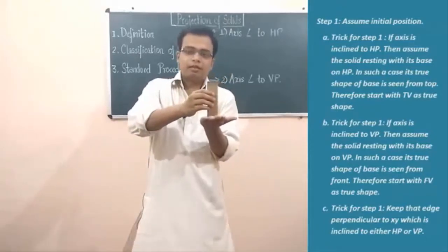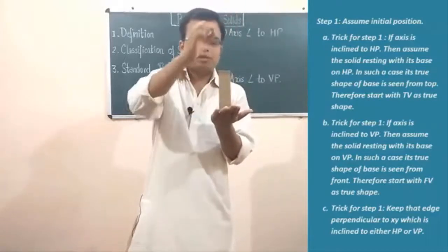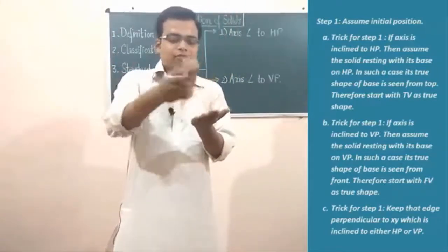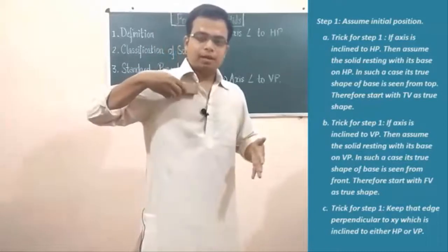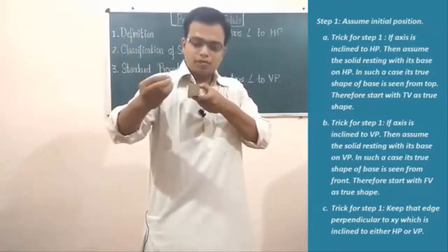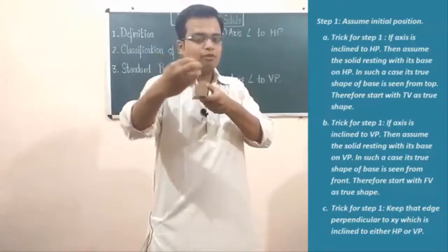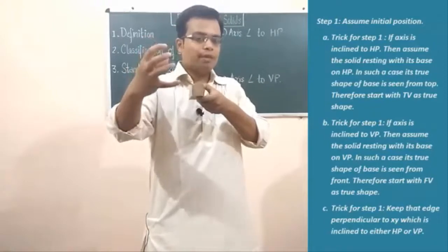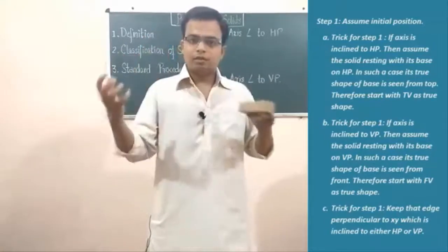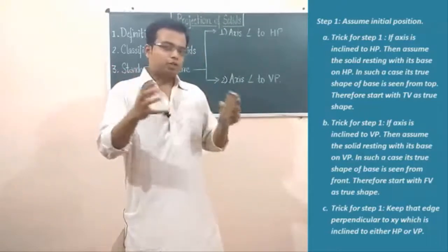Then again you need to ask the same question to yourself, from where can you see the true shape of this base? Obviously from the top. If the face is resting on the vertical plane, you need to keep it standing on VP. And then again you have to ask yourself from where you can see the true shape of this face, obviously from the front, and therefore you have to begin by making the front view first. That's exactly how you need to approach solving problems based on projection of solids.